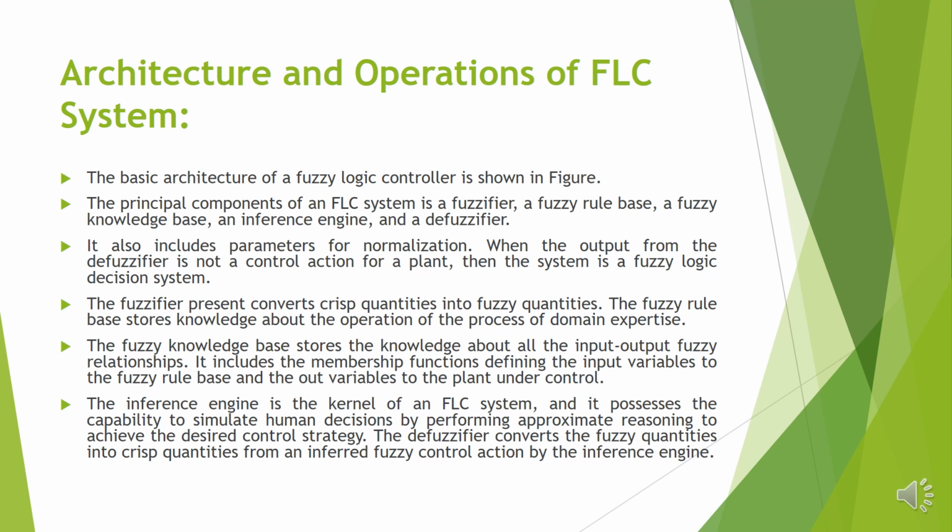We use the inference engine between the fuzzifier and the defuzzifier. It is the kernel of the FLC system and it possesses the capability to simulate human decisions by performing approximate reasoning to achieve the desired control strategy. The defuzzifier converts the fuzzy quantities into crisp quantities from an inferred fuzzy control action, which is done by the inference engine.